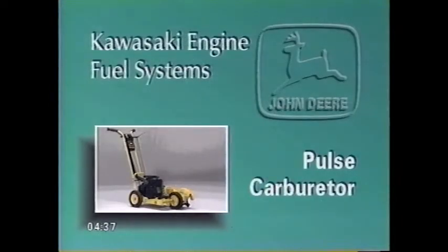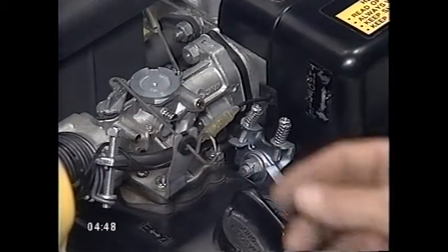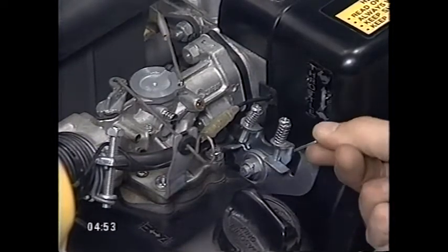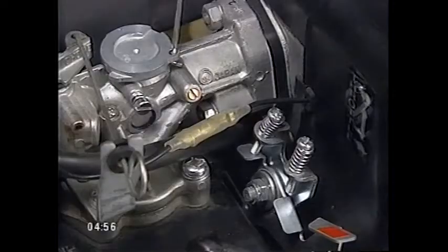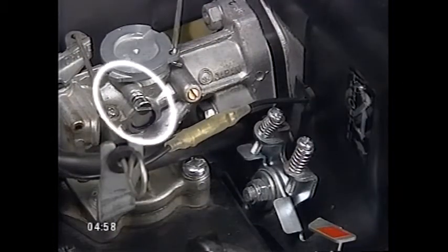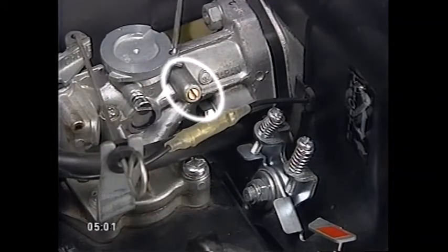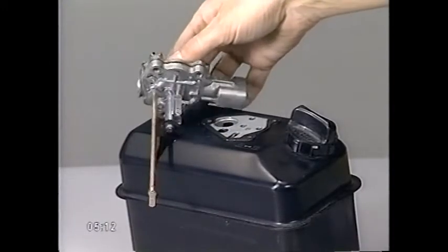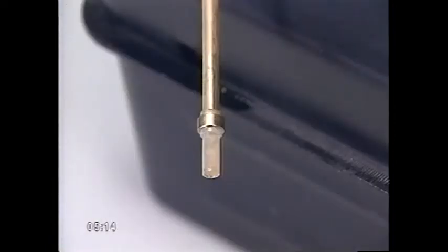Now, let's look at the pulse carburetor in detail. You will generally find them used in small engine applications, such as lawn edgers. It has a manually operated choke and a throttle valve that rotates with throttle position or the position of the governor control rod. There are two adjustment screws, one to adjust idle speed and the other to adjust the volume of the idle fuel-air mixture. The fuel pump section has a long fuel intake pipe with a strainer at the end to filter foreign particles out of the fuel as it is drawn out of the tank.